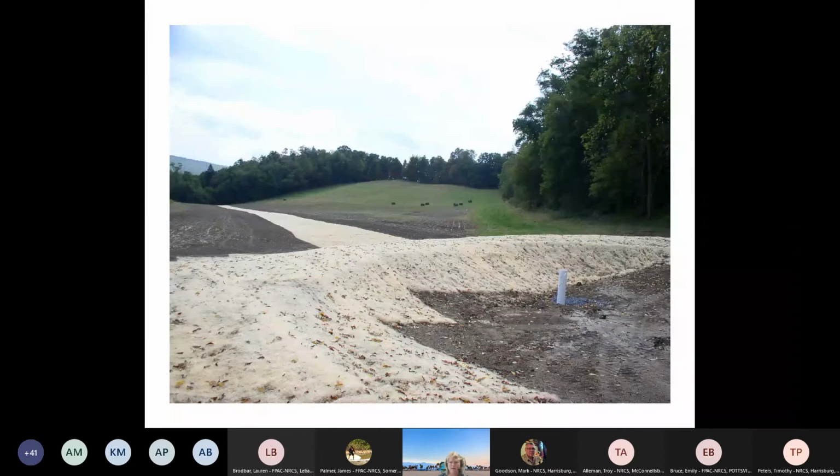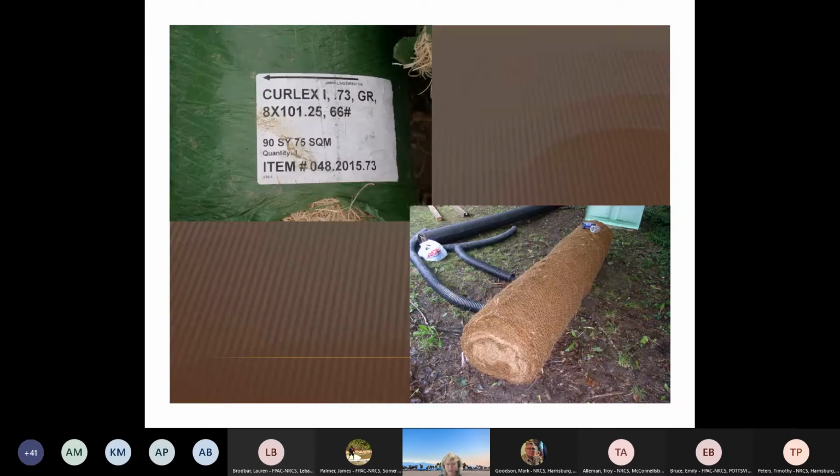And then at the end of that culvert, this low flow water is going to be directed to this basin, which will go into a pipe. You can see the riser, and then it'll kind of protect the waterway from the low flow, so your grass can get established. So the water will be conveyed to an outlet from the basin, and if you get a bigger storm, it's going to go over this bank and then down through the waterway. And then as inspection occurs during, checking the materials, making sure it meets our standards and specifications.